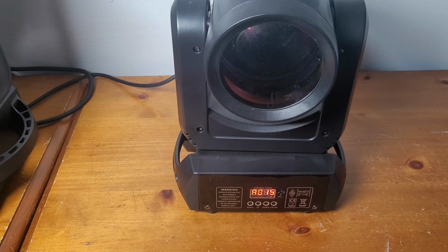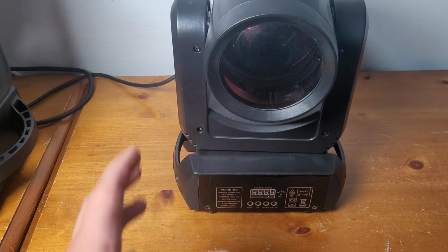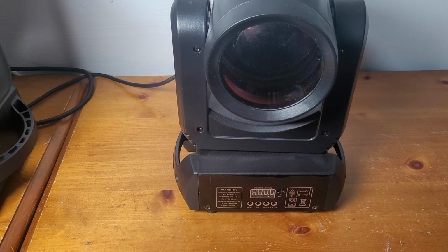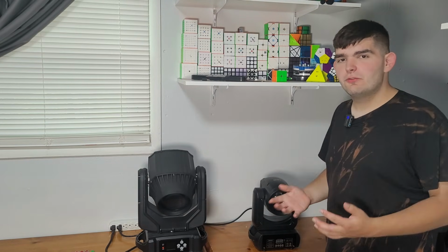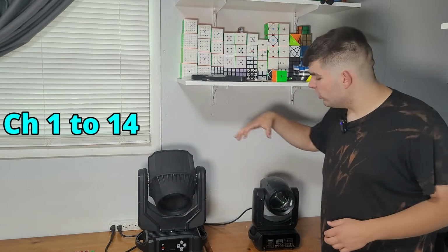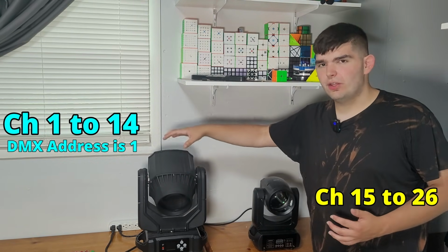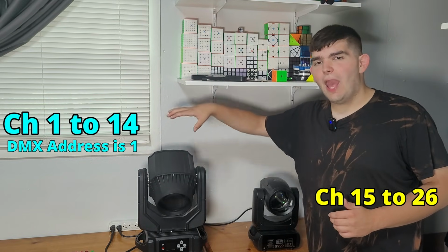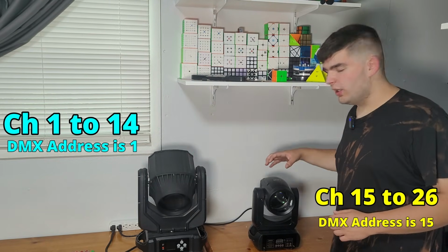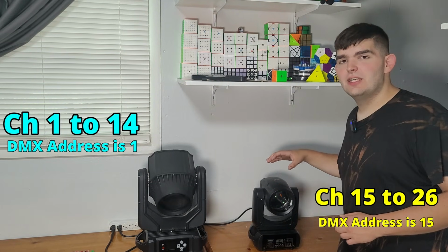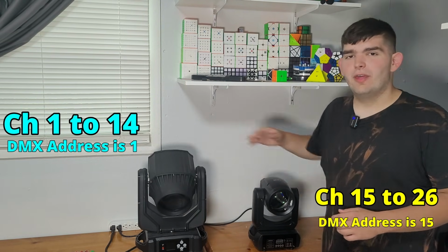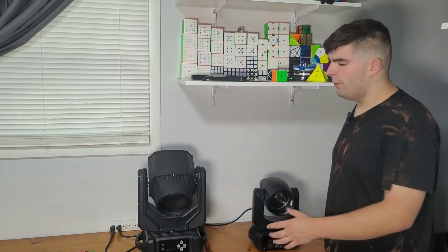Now it's set for channel 15, which means this moving head will start reading data at channel 15, and it will read the next 12 channels after that, since this only needs 12 channels. So this whole setup would use a total of 26 channels, the 14 from here and the 12 from here. We have the start address on this one set to 1, since there's nothing before it, so we could start reading it at 1, and it ends at channel 14. So we have this one and the DMX address on here set to 15, so we can read the first open channel after this. Now if we were to start a new chain and hook up a different chain to the controller, that would have its own universe for it.